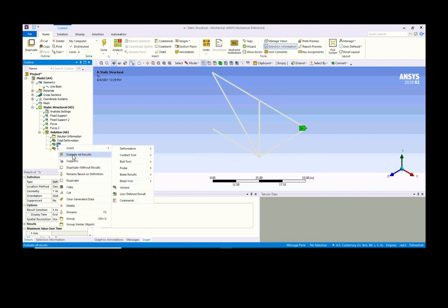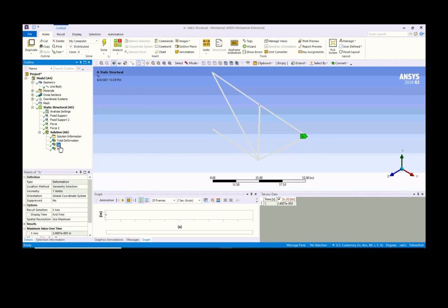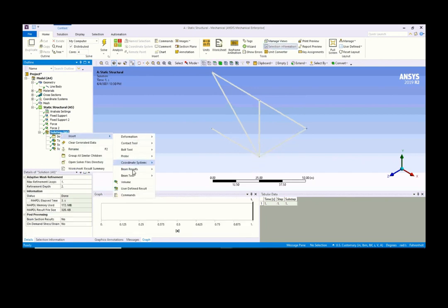So you can evaluate all results again. Then that gives us the result of 5x. The result in the x-axis, and this is in the y-axis, 0.019231 inch. So you can compare with our manual calculation, which is 0.0195, compared to this calculation result from ANSYS, which is 0.019231. Of course you can do the same for other nodes if you want.